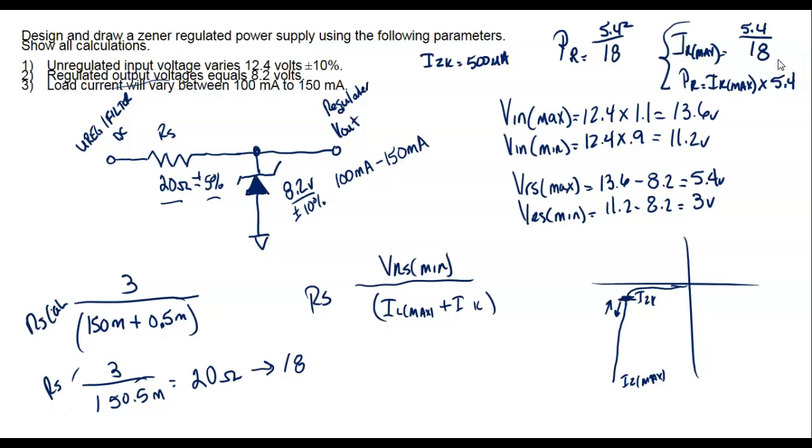Really? P equals V squared over R. Huh? You did 15 squared again. Yeah, I know. So we calculated PR and we calculated what? Yeah, but what did we come up with? So it means we would have to use at least a 2 watt resistor.